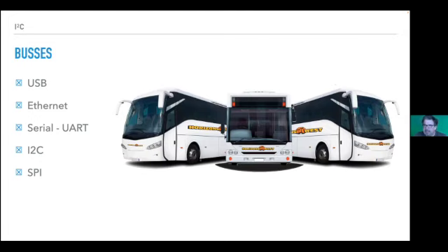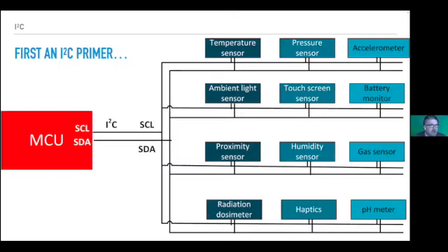And then it says, listen, if I'm being requested, then I know I'm allowed to talk. If there's two chips, two Peters in a classroom, then they both talk. The same here. So you have to make sure that they have different addresses. Okay, so I'm going a little bit further into I2C because that is actually what we are talking about.